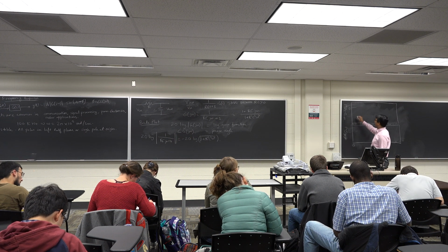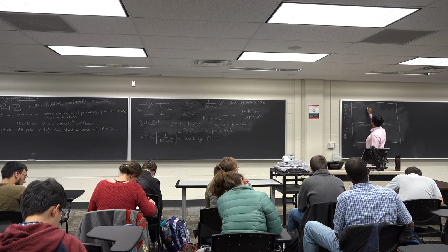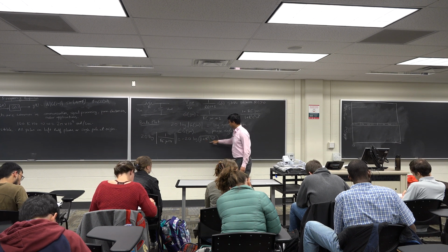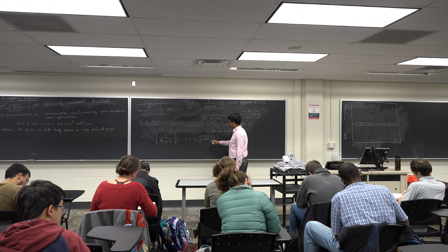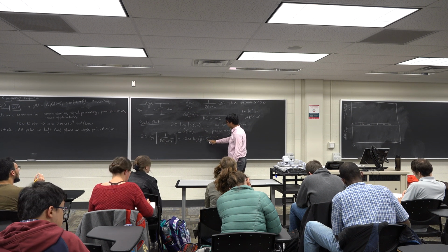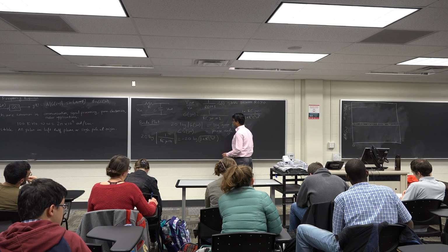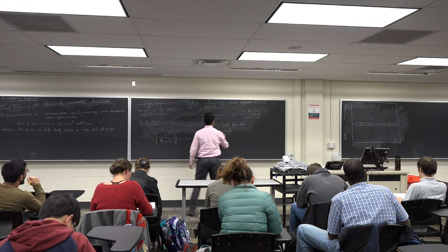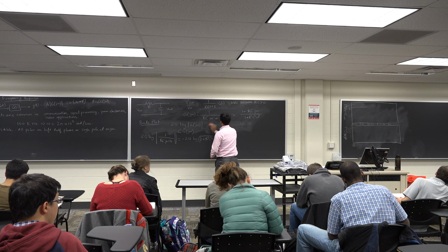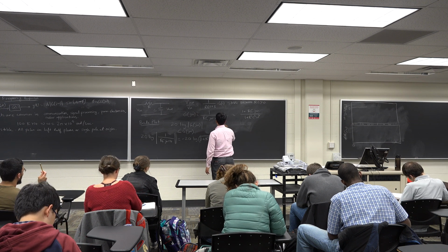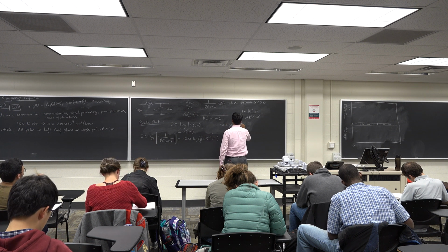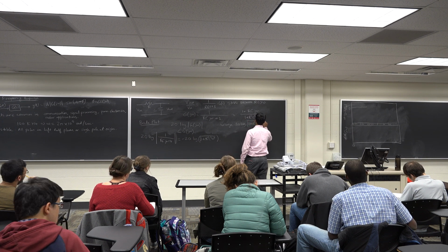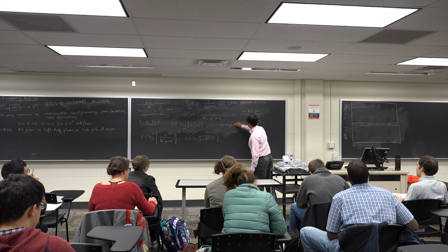So for small values of omega, it's equal to 0, and for large values of omega, this function behaves as follows. So for omega large, it is minus 20 log of the square root of 1 plus R squared C squared omega squared.